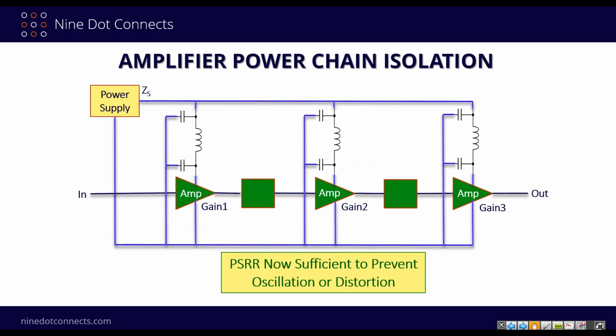So I've drawn a pi filter here, and the goal is to make it so that the rejection from the last op-amp into the power supply line, coupled with the rejection from the supply line into the first one, gives us a double shot at reducing it. We've pegged those inductors down at both ends, so we have an excellent rejection.